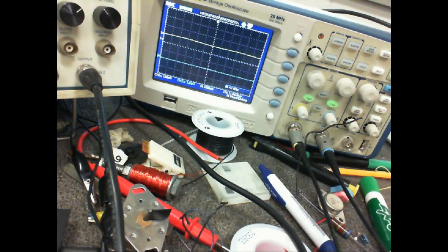We'll see how we can eliminate that or make it negligible with the type of cabling and stuff we do now. And this will make sense later on, why we do things the way we do. Why, when you take that thing apart, you can't untwist those wires. If you untwist those wires, then it's going to pick up a lot of EMI. If you do twist them, then it'll have the right impedance and you get the loading and everything that we need. So we call these twisted pair cables, and you'll understand why they're twisted.